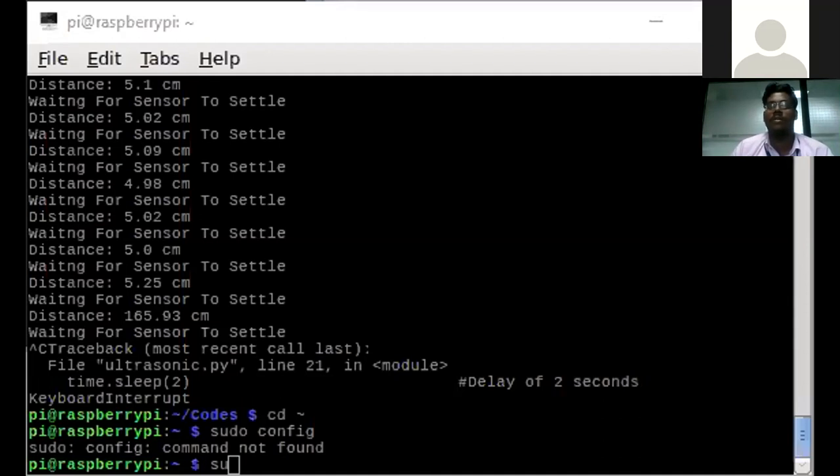So once the ISO image has been downloaded from raspberrypi.org, we need to burn that ISO file inside the SD card. So we just plug in the SD card and format it using any SD card formatter app, and then burn the ISO file inside the Raspberry Pi. Here I use Balena Etcher, but you can use any OS image burning application to burn the image inside the SD card.